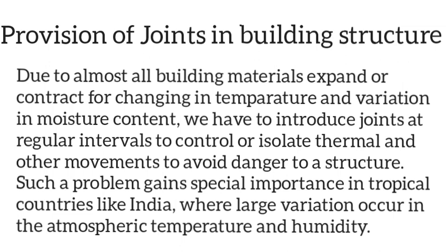In a continuous structure, the cumulative effect of dimensional changes in the building elements may be considerable. In case components of such a structure are not allowed free movement, internal stresses will be set up which may result in formation of cracks. This may in turn endanger the stability of the structure.